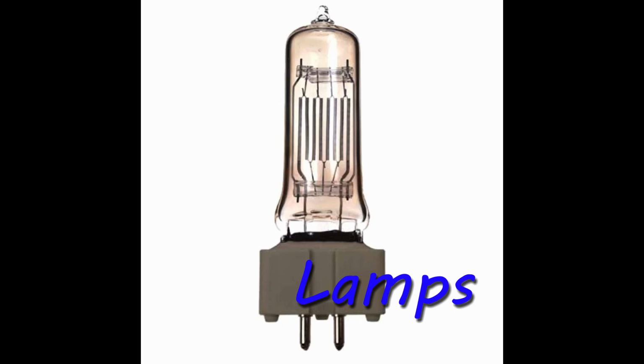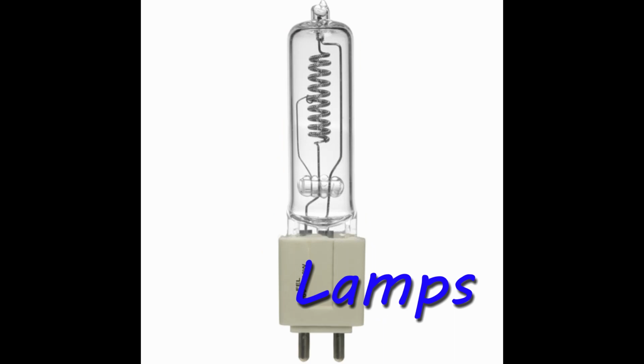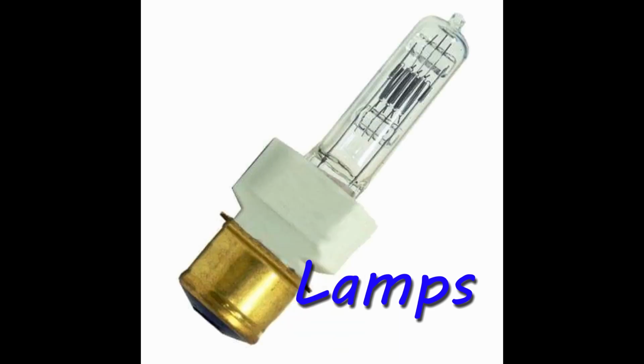There are many different types of lamps, different base mounts, different lamp shapes, and different wattages. You want to make sure that you understand the correct lamp type that fits that fixture. There is usually an optimal type and wattage for each fixture. Putting in the wrong lamp could minimally degrade the efficiency of the instrument and at most damage the instrument because of misalignment. Consult your manufacturer's specifications to make sure you use the right lamp.